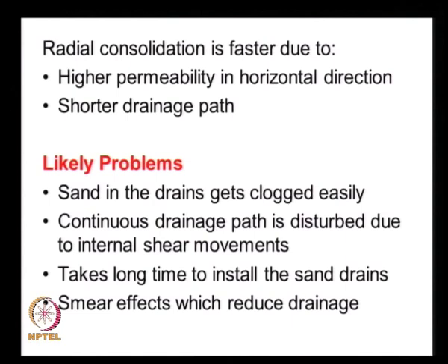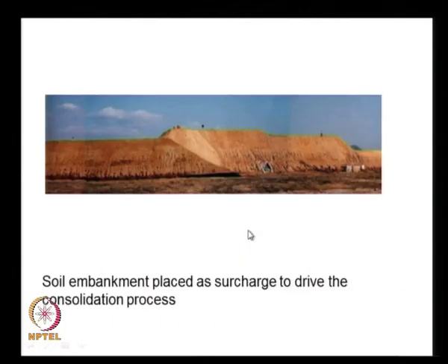Because of all these reasons there is a need to come out with better methods for accelerating the consolidation, and the introduction of the geosynthetics has helped in completely transforming the way we look at this problem of the pre-consolidation. And here we see an example of a soil embankment that is placed to drive the consolidation, and we all know that unless there is an increase in the effective stress, the consolidation will not happen, and the increase in the effective stress is achieved only by increasing the total stress.